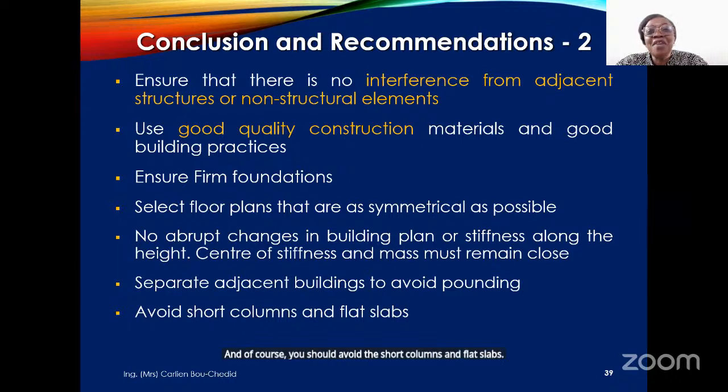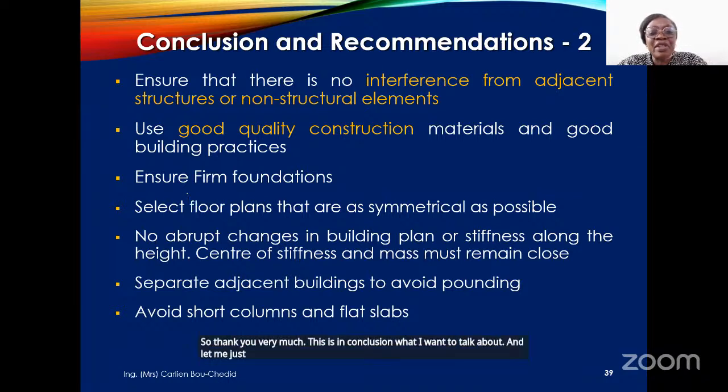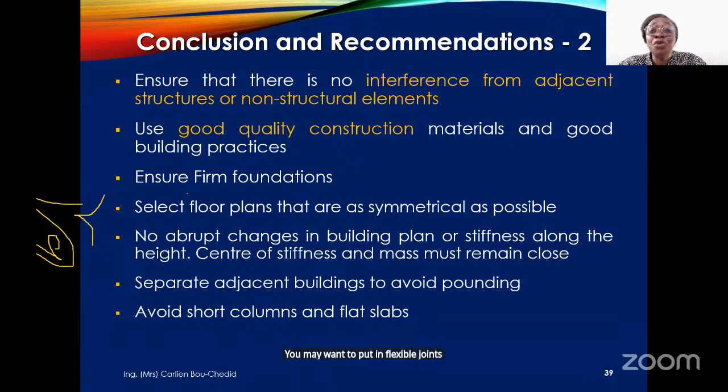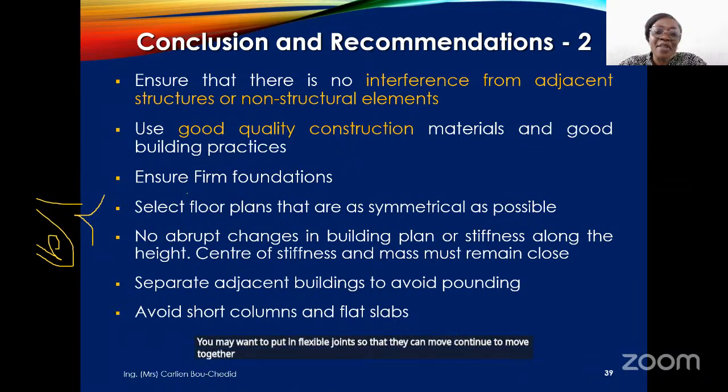So thank you very much. This is in conclusion what I want to talk about. And let me just add that although I have been speaking about buildings, the same principles go for any seismic resistant design. If it's pipe work, you may want to put in flexible joints so that they can continue to move together without any breaking. So thank you very much for your attention.